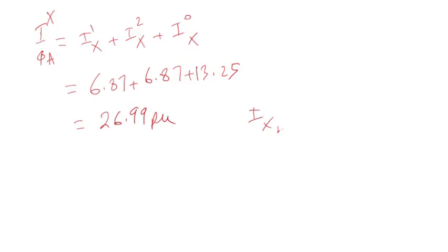So I base is 100 MVA divided by 138 kV times square root of 3, which is 418 amps.